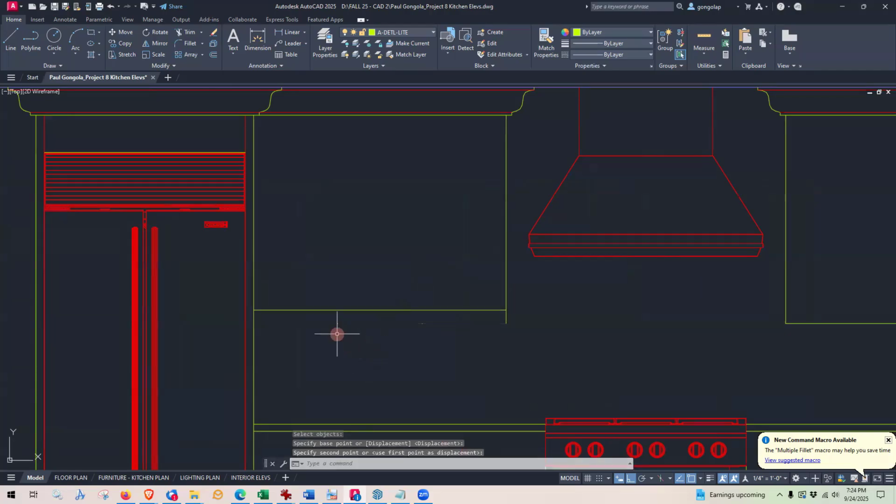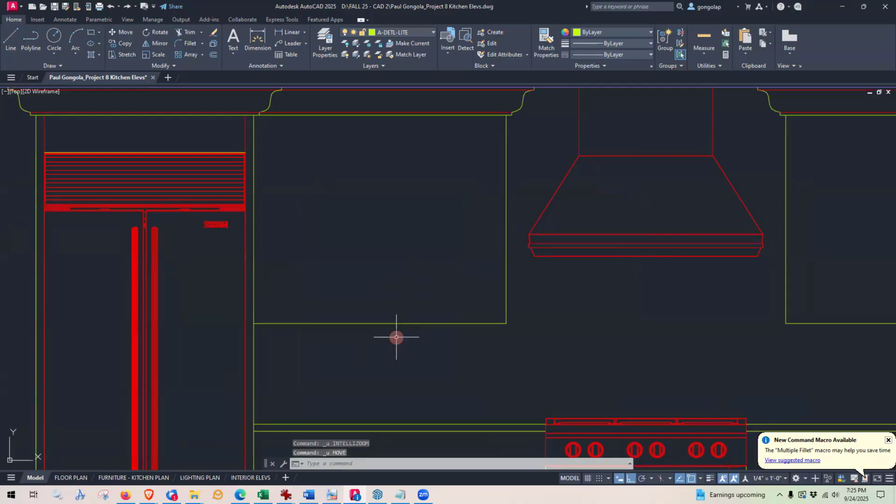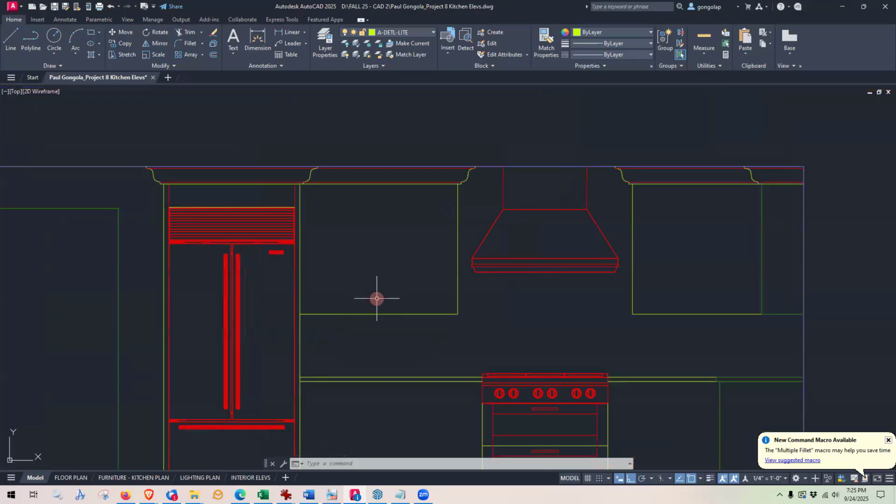So you can see that what it's done is, hopefully you can see this, it has put a little dot here and a little dot here. It's called a node in AutoCAD, but it's literally a dot. So I want to move that line back down. And those nodes are at third points right here, and they are dividing this into 3 equal sections.